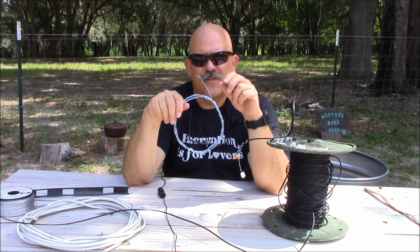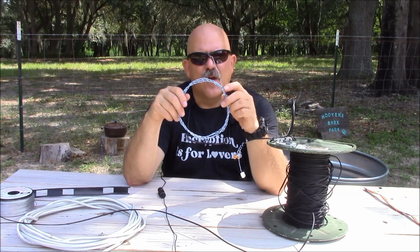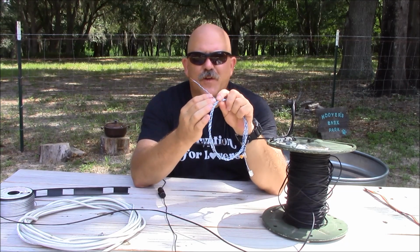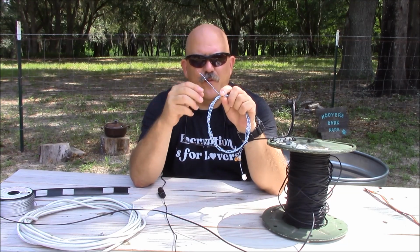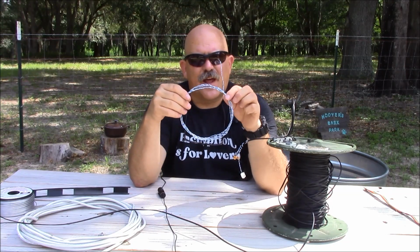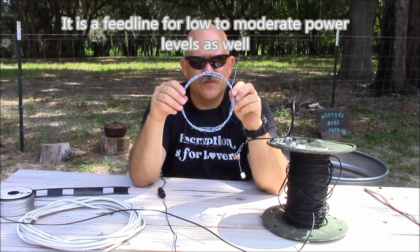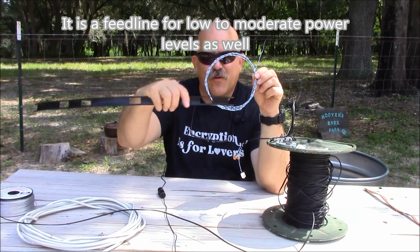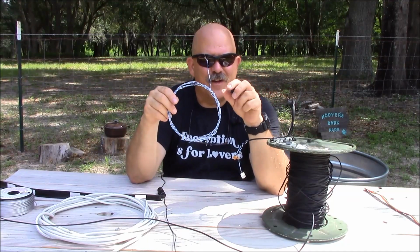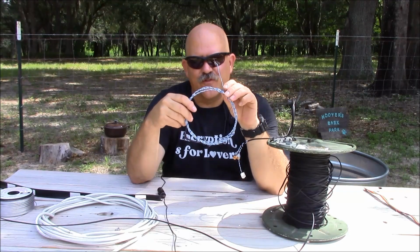The balanced feeder that's the easiest to fabricate and roll out is just a simple twisted pair. We've taken this out of some category 5 cable, and you can see we have two conductors and they're consistently spaced and insulated from one another by having a uniform twist across it. And having something like this allows this to function as feed line. Now, is it going to be a lossless feed line? No, not at all. This is going to have much more loss in it than a pre-engineered RF feed line such as coaxial cable or your window line, but it's going to allow you to establish a talk path with just the resources that are available to you.